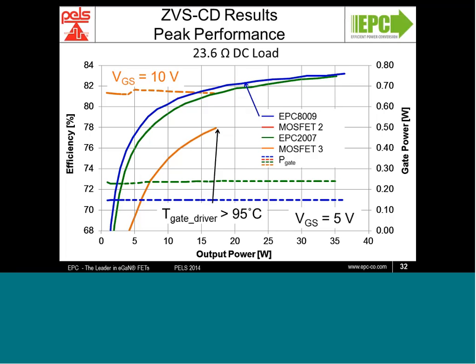And lastly, we have the strong contender MOSFET, in this case the logic level FET. You can see that it did reach 35 watts, but it just didn't quite make the 82% mark in this test. The gate losses are comparable to that of the EPC 2007.